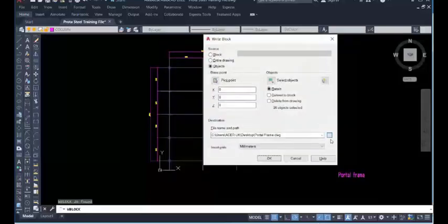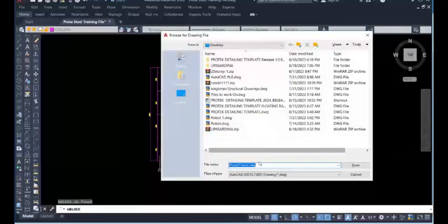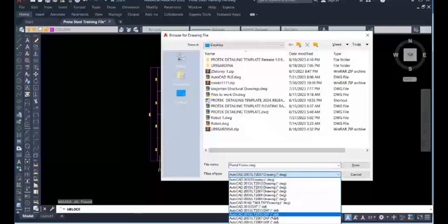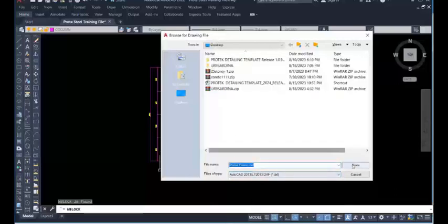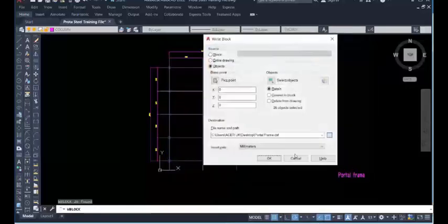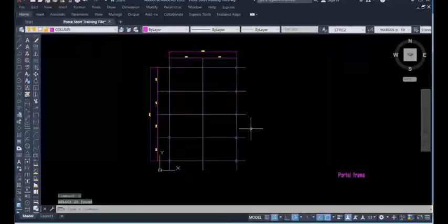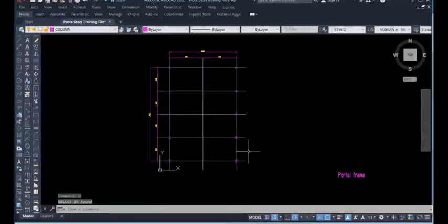The next thing you are supposed to change there is to change it to DXF. So get back to those options, the file of type. Selecting these options, instead of DWG, select DXF. You can use any of these DXF versions right there. Click on save. After which click on OK. So that file has been saved to the desktop right there.